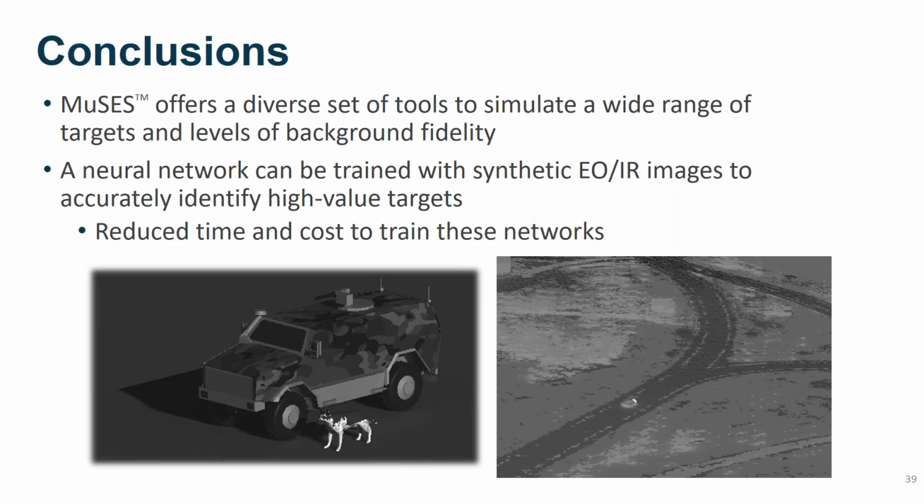And then once we have those different types of ground clutter separated into different parts in the mesh, when we do the thermal solution, we can predict the physical temperatures for those different types of ground cover, like dirt, gravel, asphalt, concrete, grass, trees. So there are built-in background models within MuSES for those different types of ground cover.